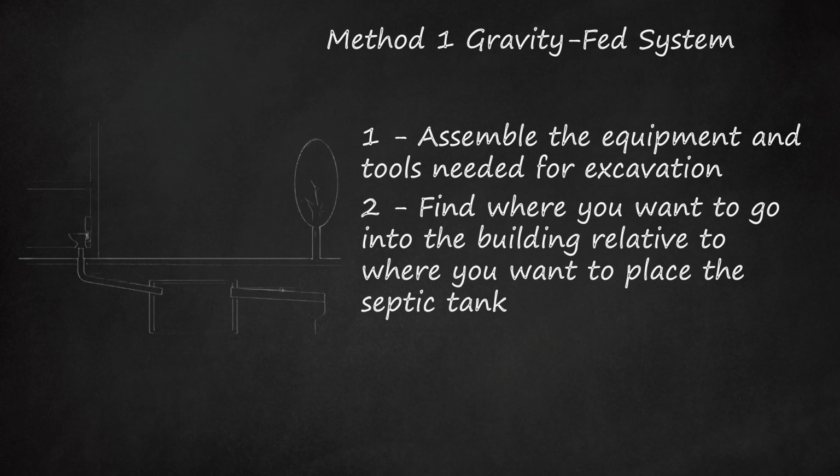Set it level where it's going through the wall or under the footing, and from there run with about an 1/8 per foot of pitch, slope, toward the septic tank. Go further or all the way into the tank if required. If not, switch to D3034 with the appropriate adapter and pipe toward the tank with 3034. Be sure to put a test cap on the end going into the building. If going through the wall, seal around the hole with hydraulic cement, inside and out.